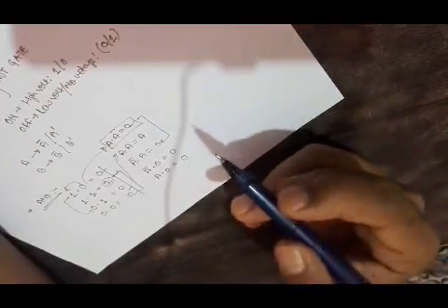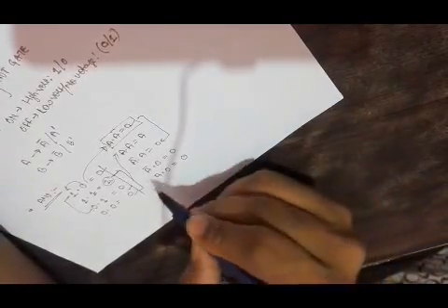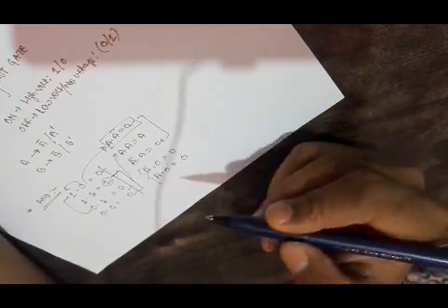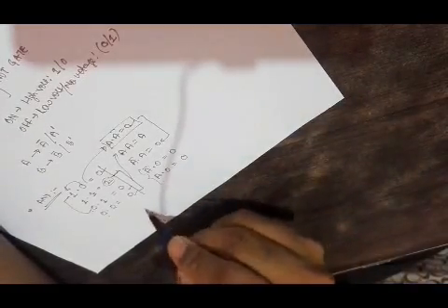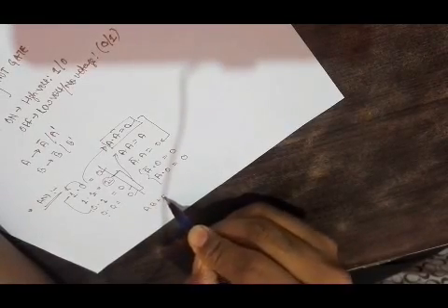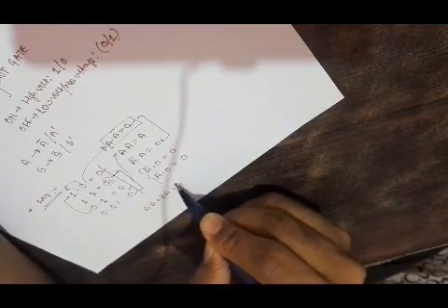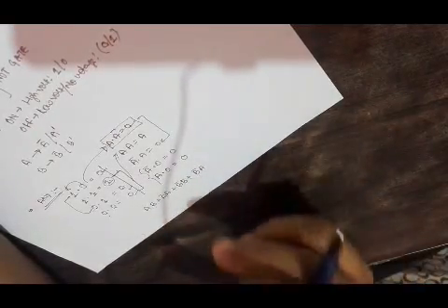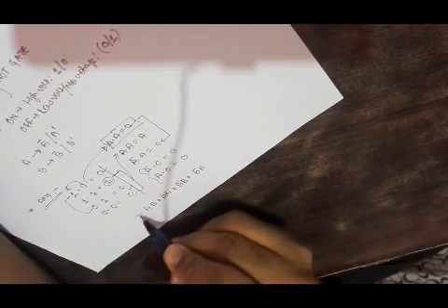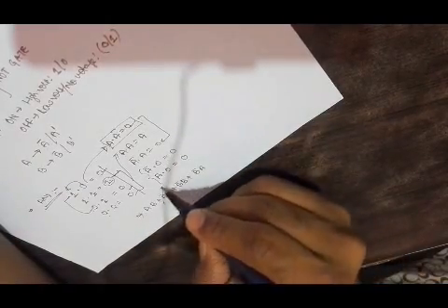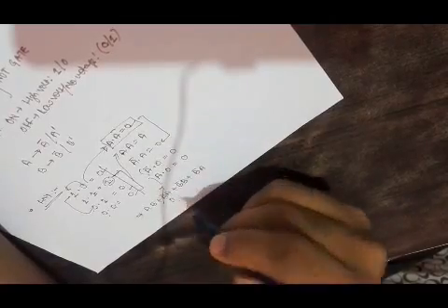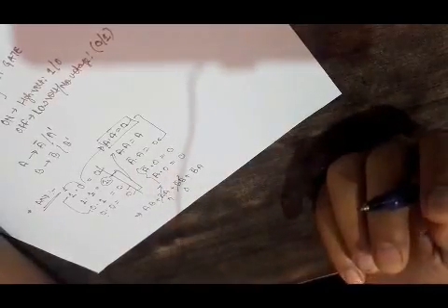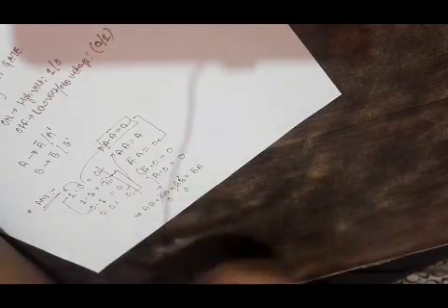This property is known as the commutative property, which we will study when we study about the gates. And either you AND A bar with 0, output will be 0, or A with 0, output will be 0. So if we have some expression like A B plus A bar A plus B bar B plus B bar A, and this is a logical expression, when you use your Boolean algebra to simplify this, you will straight away make this 0, right? A bar dot A is 0, B bar dot B is 0. In place of the A variable, if you use the B variable, B bar B is also 0. This we get from the AND property, okay?